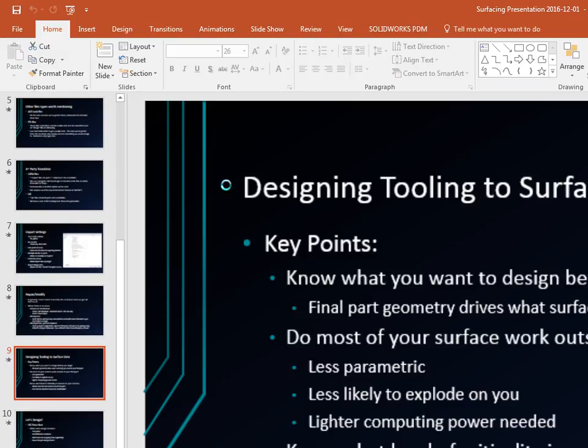so I'm gonna take this face here, and I'm gonna just make myself a new surface to say, okay, I want to replace it with this surface. So I'm going to do a 0 offset and then take that, untrim it so it gets some square edges. Oh, take that face. Okay, I got to hide my body here a second. All right, take this guy, untrim it, all edges. Oh, I wanted it to merge. Shoot.